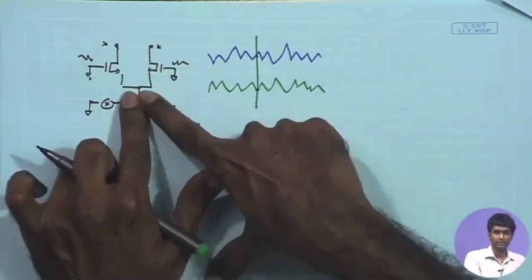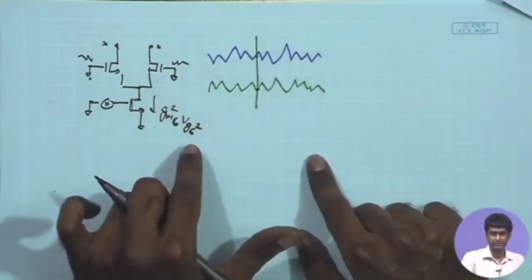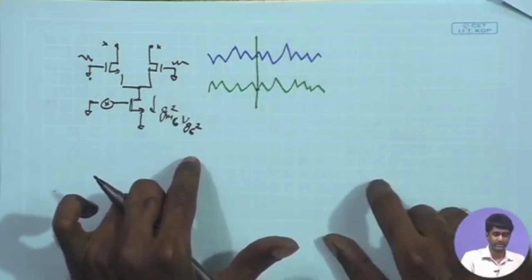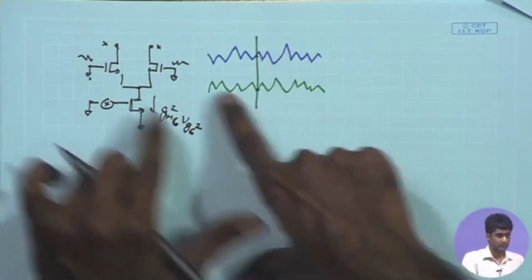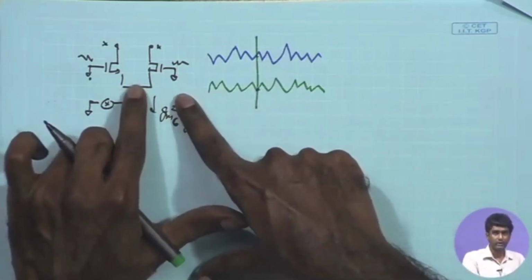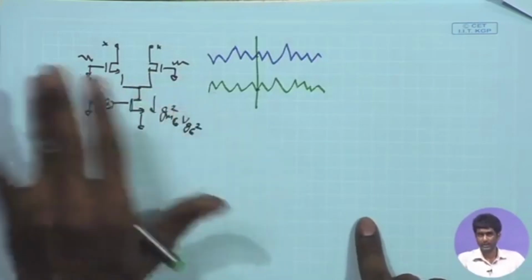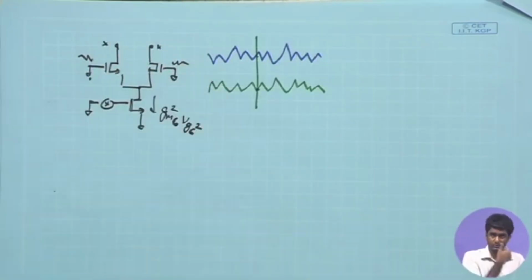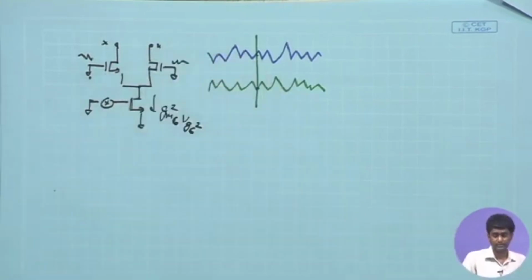Common mode signal does not get significantly amplified, only the differential part gets amplified and appears at the output with a much magnified response. Therefore, we are considering only the differential response, and doing that we look at this as an AC ground and then figure out the total output referred noise and the input referred noise. So this is another point we should be taking note of with respect to the overall analysis.